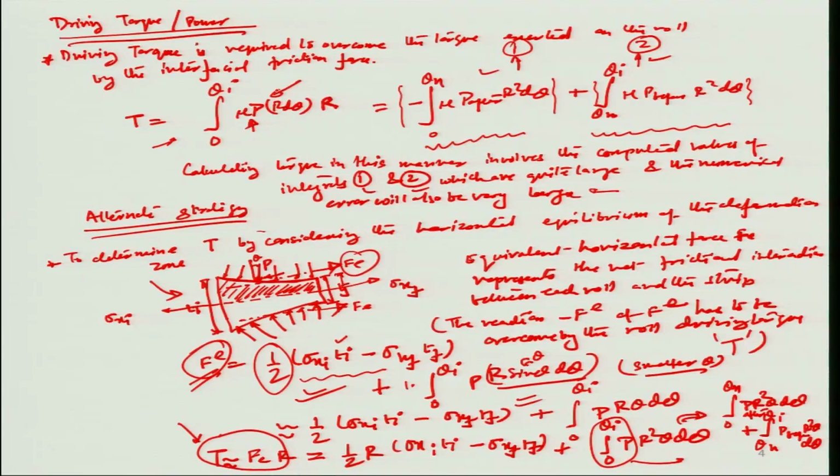role of friction here, you basically try to find out what is the force that is needed for pushing the element, and that is assumed to be, if there are no other energy losses, the same as the force that is needed for pushing the element forward, or the friction force on the roll. So there is no loss between these two forces, and they are equal and opposite to each other. So therefore that is an alternate strategy to calculate the torque value.